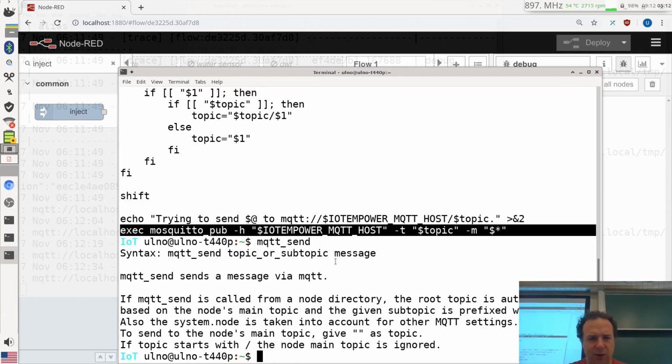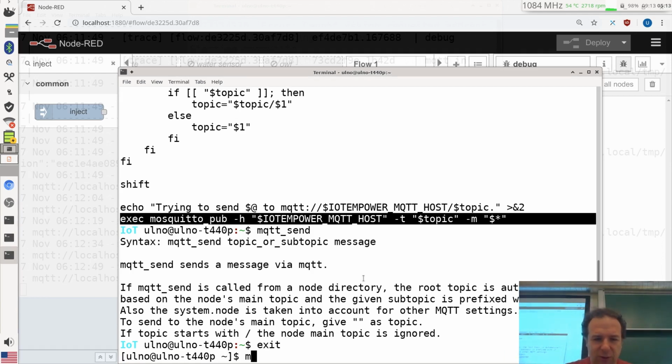And if I call this alone, I think it gives me a little help. So MQTT send needs a topic and a message. I have to do Mosquito direct. Sorry guys, because I don't have the Pi available. So I do a Mosquito pub to the host, localhost, and with the topic test and the message hello world.